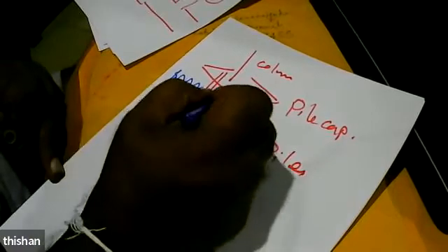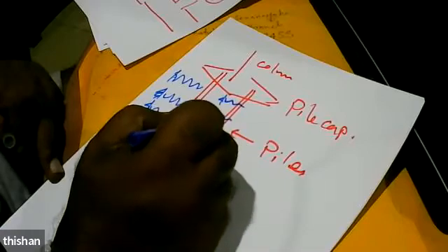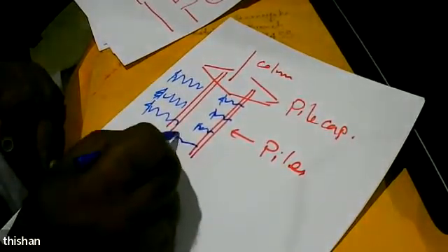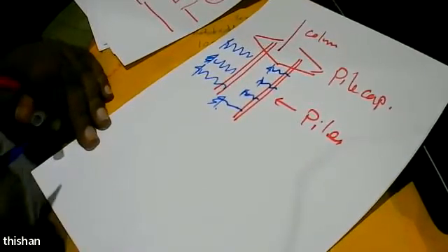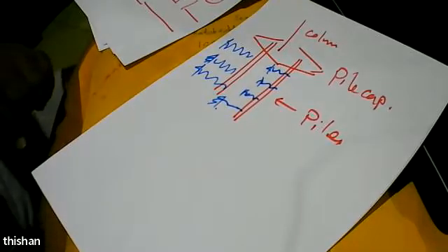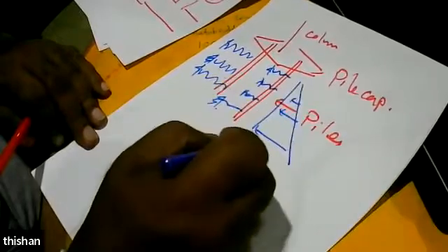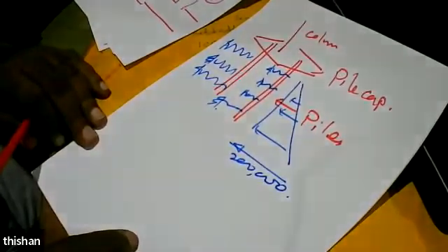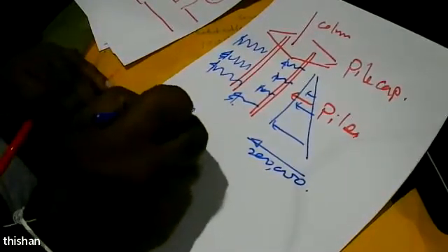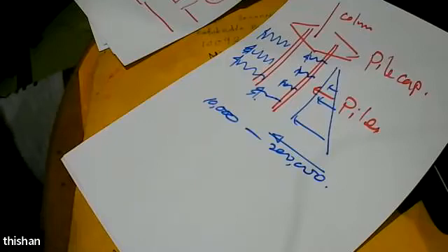There are equations to calculate the spring stiffness. So you'll put some springs and represent the soil. And for these lateral springs, there are special ways, so I will cover that separately, because the stiffness values can vary like this. It can become very strong if it is good soil, and it can vary from 10,000 to 200,000. So we call it Winkler springs.